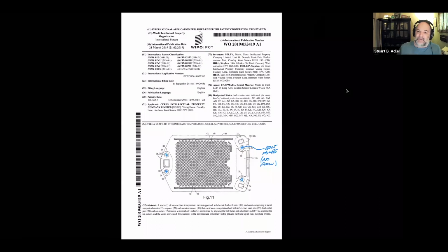That can lead to problems in the operability of the stack, because if you start pulling more current, all of a sudden you could exceed 100% utilization on one of the cells, and that causes a voltage reversal, which then destroys those cells. So a common way that stacks fail is through this problem of maldistribution, or the fuel not being uniformly distributed to all the cells.